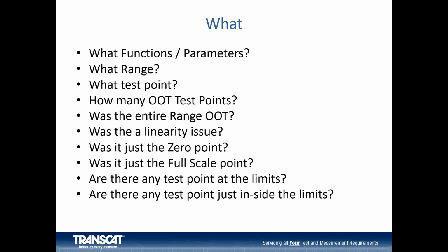The quality of the calibration and quantity of the data available can have a tremendous impact on narrowing your scope of investigation. This is why you need full calibration data as found and as left and uncertainties. The more data you have available to you, the better decisions you'll be able to make.